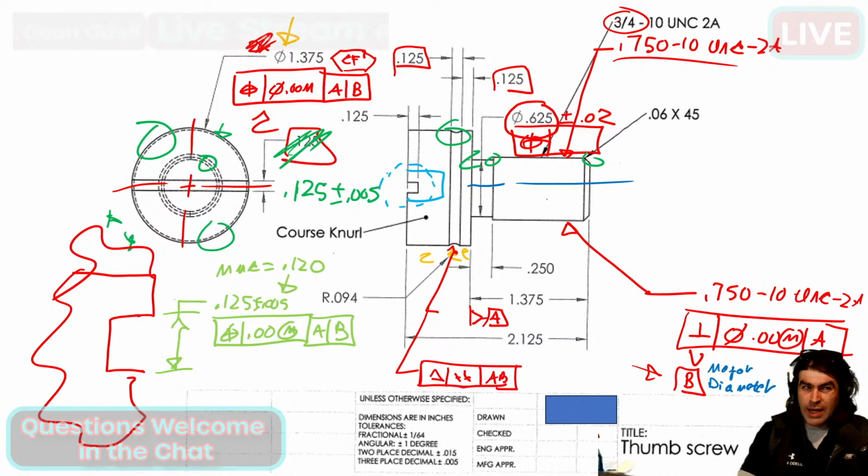Now, why do I not recommend this option? Well, now we have part of it that's not dimensioned, right? So we've got this little spot down here, which probably doesn't matter, right? We could say, whatever, we'll just put a plus or minus dimension on it. And you could do that, but say your checker walks by and is like, hey, we're not doing plus or minus dimensions to locate surfaces. Haven't you heard about 2018? ASME Y14.5-2018. Can't do that anymore.